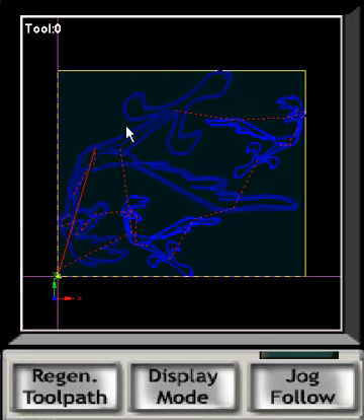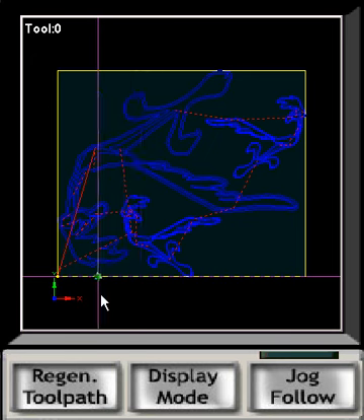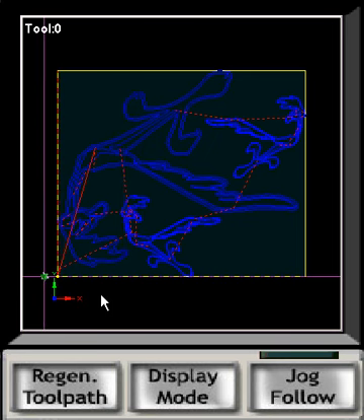As you can see, when you load the file, there's a few differences from the old toolpath. First of all, your crosshairs, these purple colors here, originate at the tool and show the position that you're in. You'll notice something as I jog my x-axis back and forth here. When the x-axis goes off of the job size, the line turns red on the job to let you know that the cursor is far away in that direction.